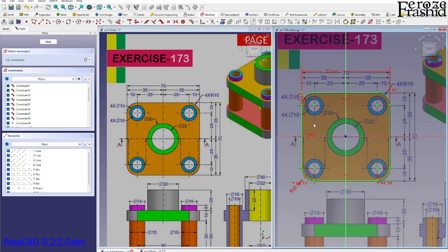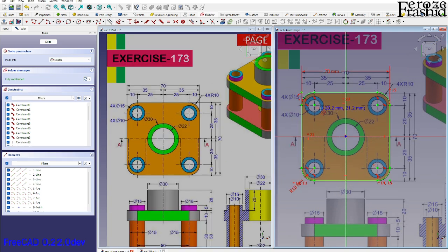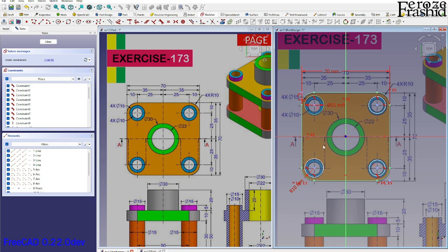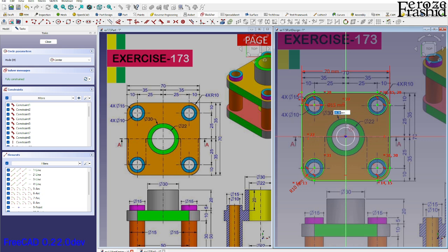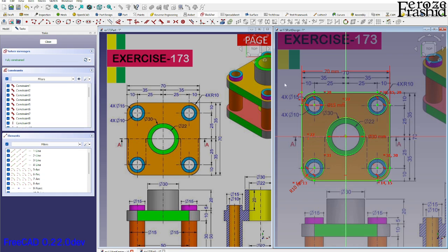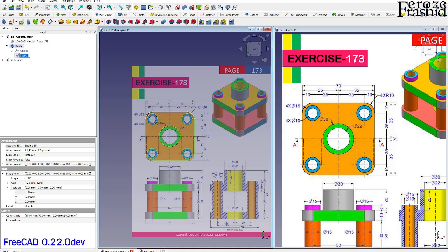So that's our outside. Now I want to draw 4 circles of outside radius 15. The easier way is to apply the dimension to one, then take the rest of the 3 and apply equality constraints. So there it is. And also maybe get this center one there. So this is 30. Okay, so this is our first sketch, and the sketching part is the same in both workbenches.